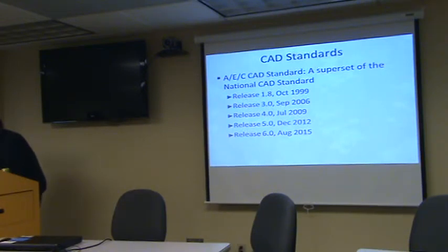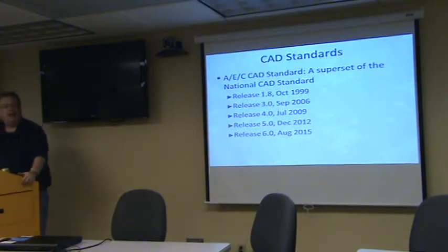I've had an issue with Revit since Revit 9.1 because Revit makes a poor DWG file. It just does, and it can't make an AEC CAD compliant standard. A perfect example is the little AIA.txt file that you use when you export out CAD files, where you control some of the symbology.